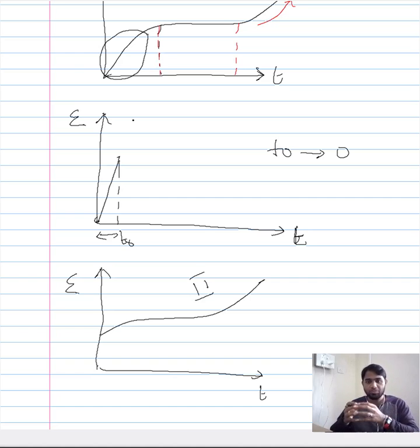In general, when you plot a practical creep curve, this region would be missing, and it will begin with something like this. A more practical one will be creep curve 2, where the instantaneous elongation of the material would be missing, and the reason for it is, unlike tensile loading, in the creep test you will be imposing the load suddenly.